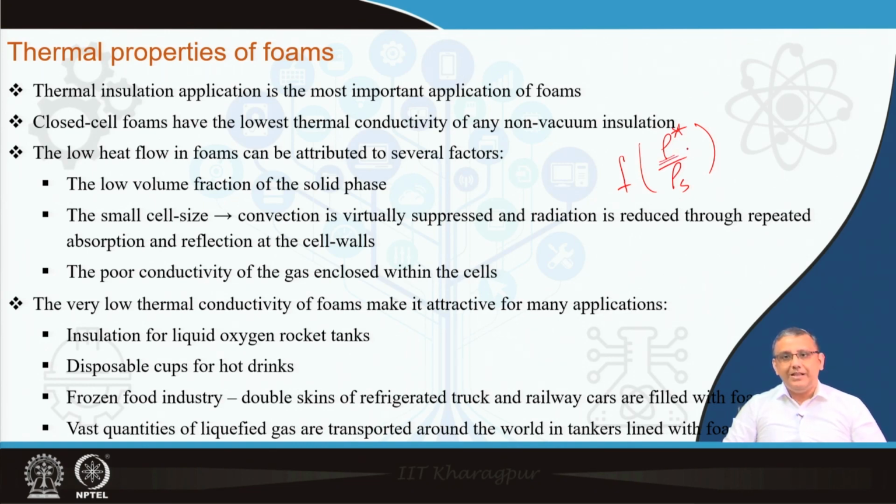This is because bulk solids, especially bulk metals, have a high conductivity. That means, if we want to fabricate a material with high insulation properties, then we should reduce the amount of bulk solid in the material, and that actually gives foams extreme engineering capability, because fabrication techniques and material design selection can reduce the value of rho star, and by doing so we can have materials with a very small amount of solid material and low thermal conductivity.